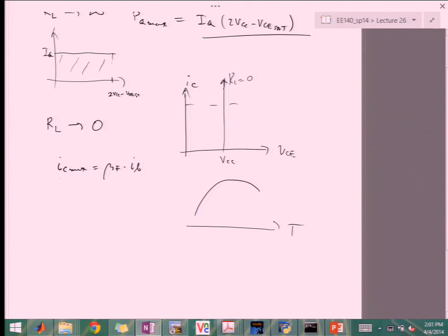And also with very high collector currents, it starts degrading, right? So as you start increasing IC, beta is going to be going down. So you may get some self-limiting in that sense. Or IB will hit IB max, and this will be from the driver. However, here you're risking that maybe it gets limited, maybe it doesn't before it blows up.